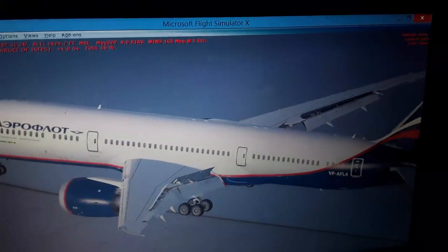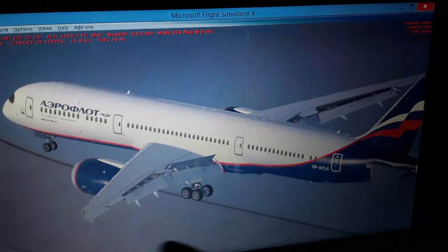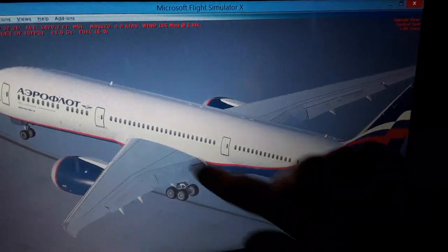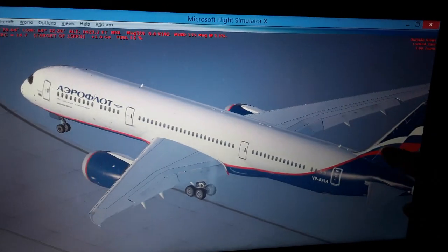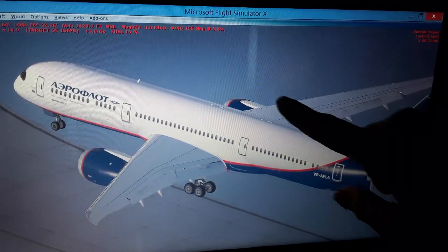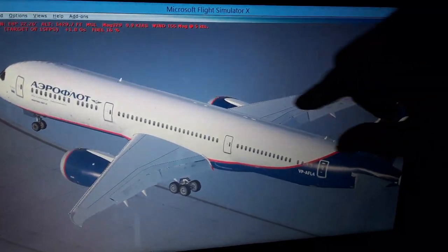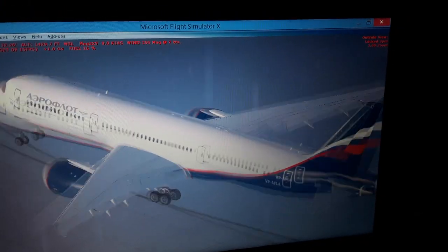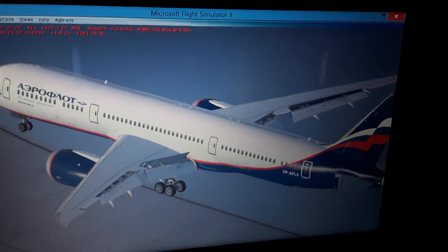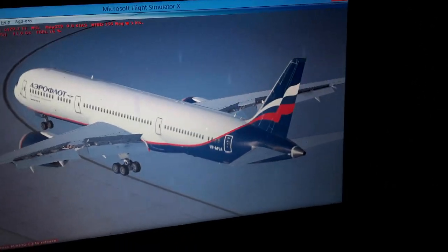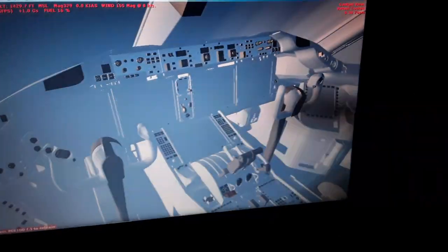Also, you can see we have differential pressure between the bottom and the top surface. The top surface of the wings has higher curvature, so the airflow is moving much faster above the wings. That creates lower air pressure, which sucks the weight and wings up into the air. So this is the main principle of the aerodynamics we need to know about flying the aircraft.